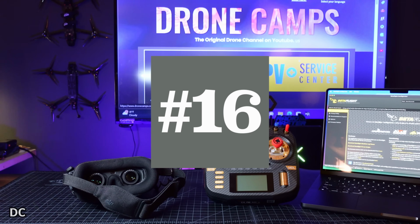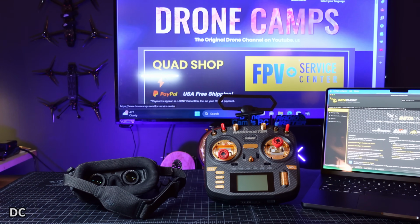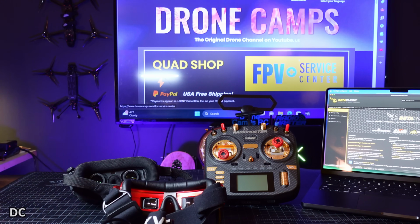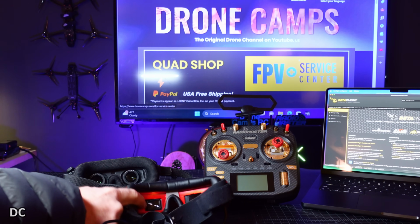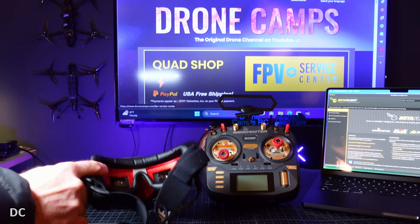Now we're going to get into some goggles tips right now, and if you are brand new to FPV, I wish someone had told me this when I first started. My first pair of goggles I took out to the field. I was with a friend. I was actually flying an RC airplane with some FPV gear that we strapped on it, and I set my goggles down on the bench, and I actually had them kind of facing toward the sunlight. What I didn't realize was that the glare from the sun through these magnifying glasses right here that magnify the screen, it burnt a spot onto the lens.